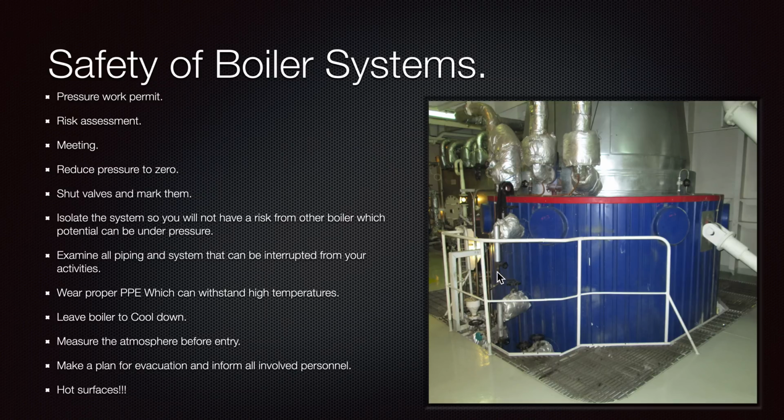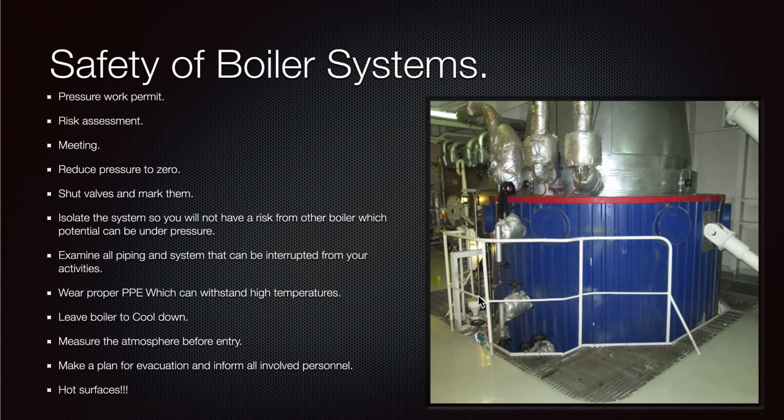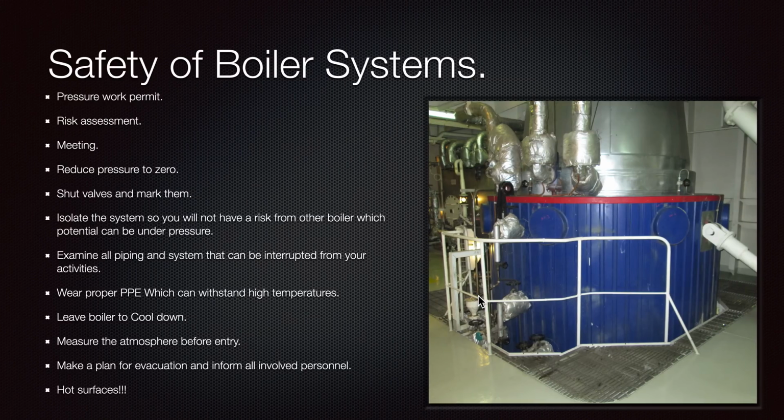So when we are opening the drain, we will see that the funnel is functioning, there is some steam coming. And at the beginning here, it's better to keep it closed, so you will not accidentally be sprayed with high temperature steam or liquid. If there is nothing running here, that means your drain is clogged. So what will you do? Again, you are not safe.